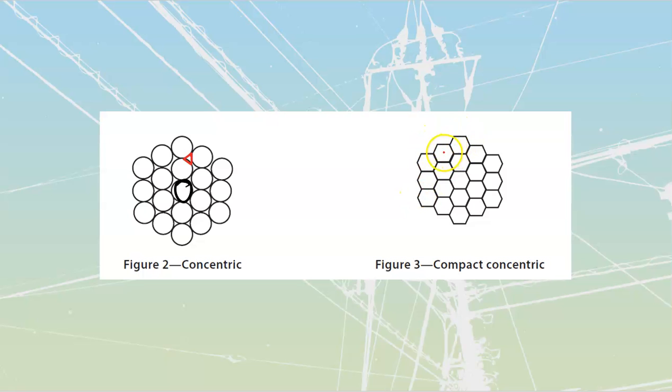Compact concentric is just going to push these together. Now it is going to be smooth on the outside. It is just a poor quality drawing for this one, but just imagine that that's smooth on the outside. If you strip these off, they're really easy to strip off the actual insulation around the outside because there's no gaps. These ones over here, standard concentric, are really hard, particularly some of the older cables that you might run into in some installations, because when they place the plastic around, that plastic flows in, and sometimes it flows in and underneath like that.